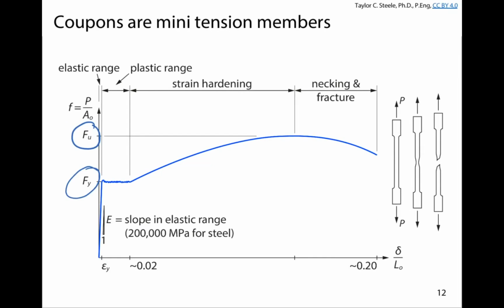We have yield, which means that it's starting to no longer be linear. We stretch the brace significantly, and there can be a lot of movement. And what's very important here is we have a significant reduction in stiffness, right? E here is basically 0. There is no stiffness associated with that coupon when it's yielding. You're getting a significant amount of stretch for no additional load.